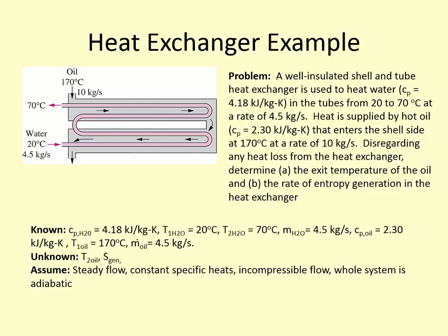Okay, so if heat is being exchanged between the two fluids, not by direct contact or mixing, but by virtue of this heat exchanger, how do we find the exit temperature? Energy balance. Okay, so thinking back to chapter 5 for heat exchangers, we can perform the energy balance on the individual fluids themselves and then set those equal to one another, because the heat that is being added to the water is coming from the oil itself. Okay, so let's do first an energy balance on the water.